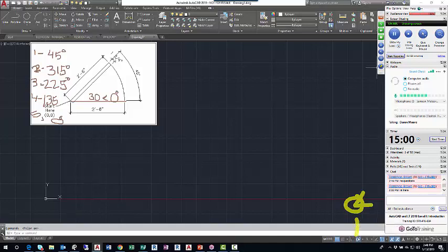I'm going to left click to turn polar on. Again, blue indicates active status on the status bar. Then I'm going to click the little arrow next to it. Ortho does not have the little disclosure arrow like polar tracking does. Ortho is on or off. When it's on, it forces you to draw at 0, 90, 180, 270. With polar, when it's on, you can open this menu and say, yeah, I want to do 90. It's just like ortho, right? 90, 180, 270, 360.